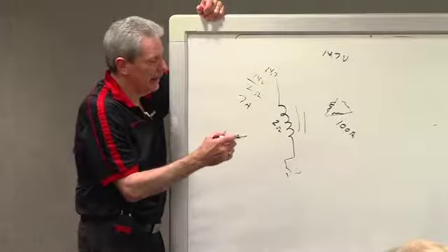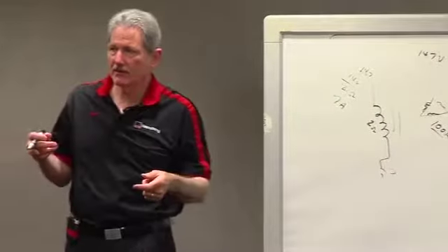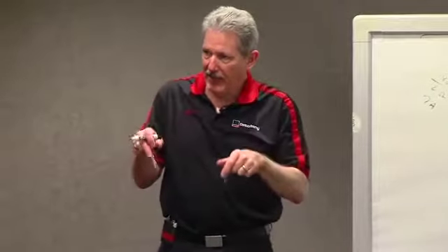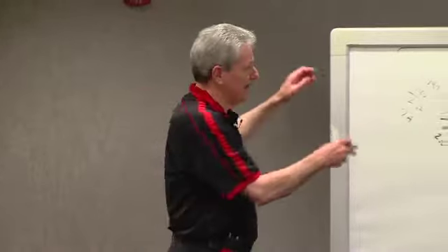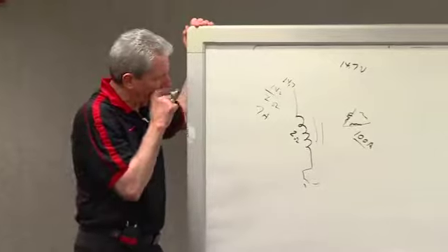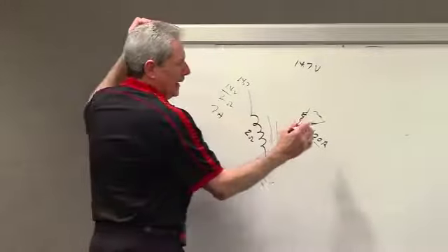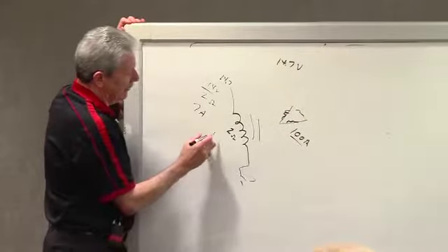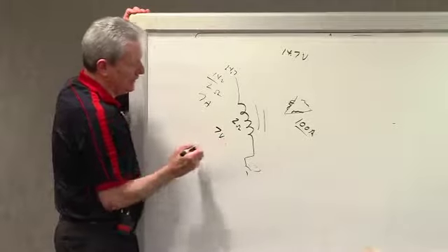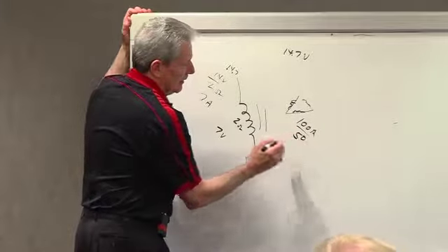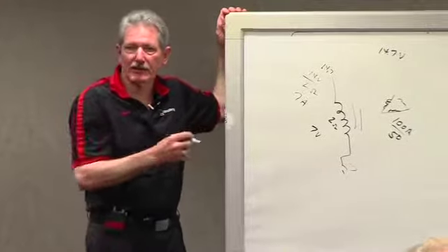Going back to Ohm's law. Well, this is 100 amps, so that means that the transfer function of this alternator, for every amp of current that I put at the input, I've got 15 amps. 7 times 15 is 100. Okay. So if I now put, instead of 14 volts, 7 volts here, that means I'll get 50 amps here, right? It's a linear relationship.